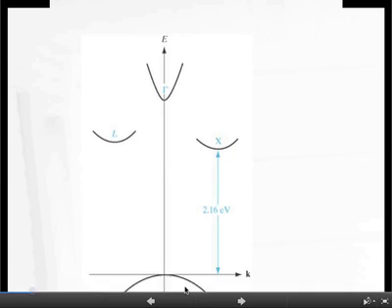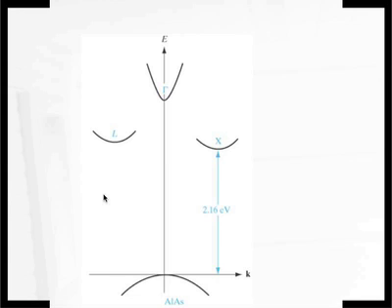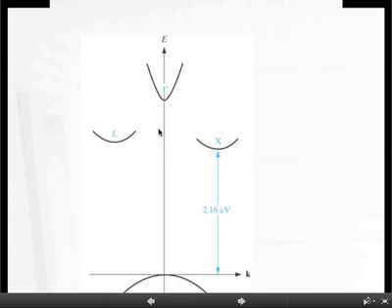Now, if you replace the gallium with aluminum, as shown here, in gallium arsenide, replace the gallium with aluminum, then you get a completely different band gap. And that's what's meant by engineering the band gap. So you can change the elements to get different band structures, okay, within some limitations. So clearly what has happened now is that the band at gamma has gone up, whereas the band at X has come down, and the band at L has come down a little bit.